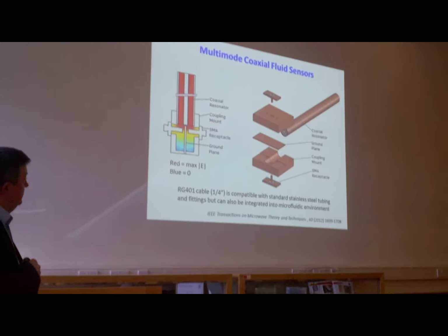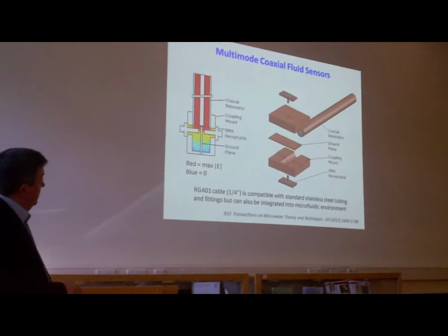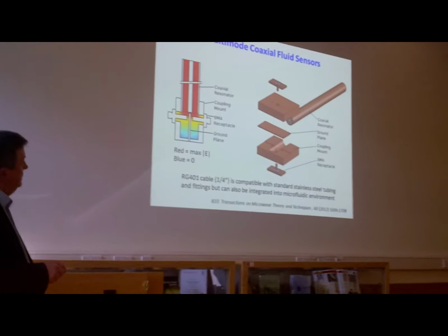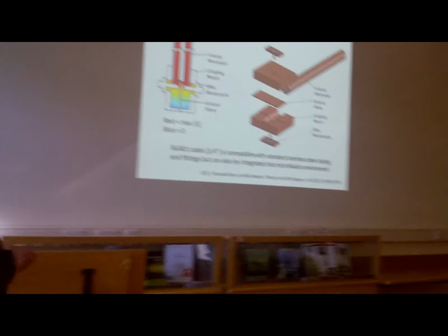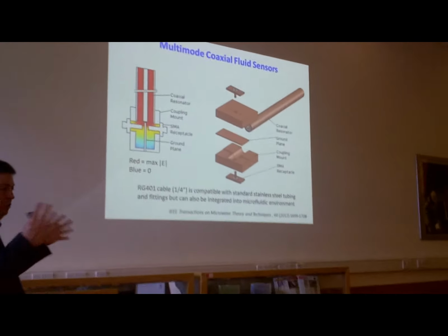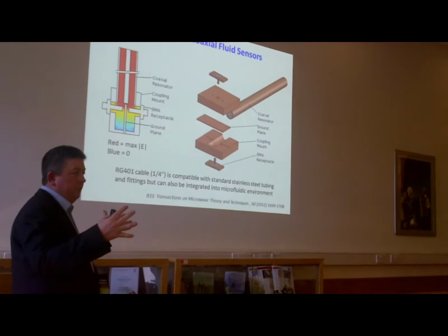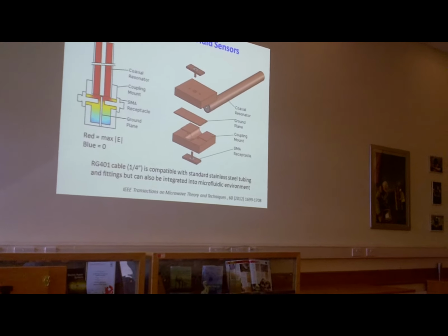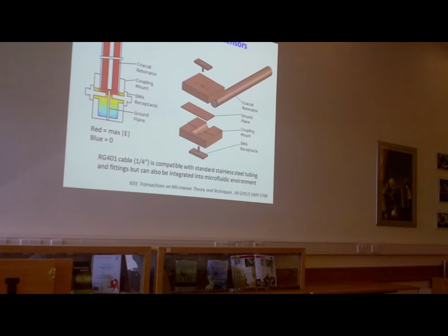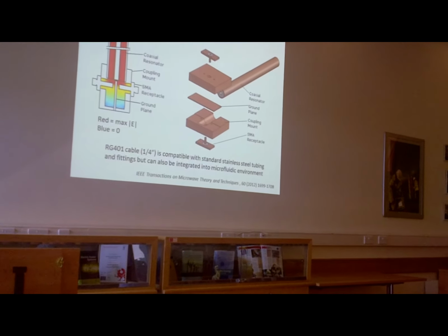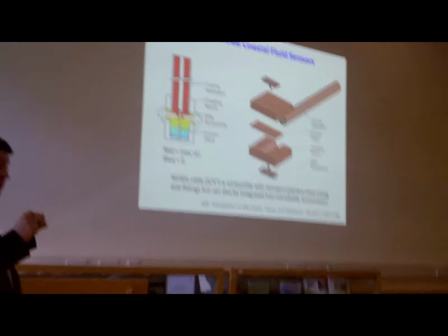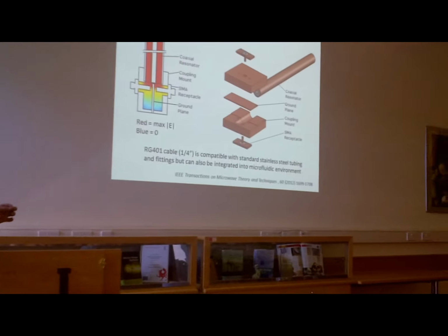So what you can see here is over a period of about a minute or so, but the collection of data here can be as fast as you want. So we can actually look at the dynamic of curing, and that's quite interesting from a polymer science point of view. But from a practical point of view, you have a non-invasive method of determining when something is cured. Again, it's simply because the microwaves sit in the background and interact with the material, and hence it's completely non-invasive from that perspective.